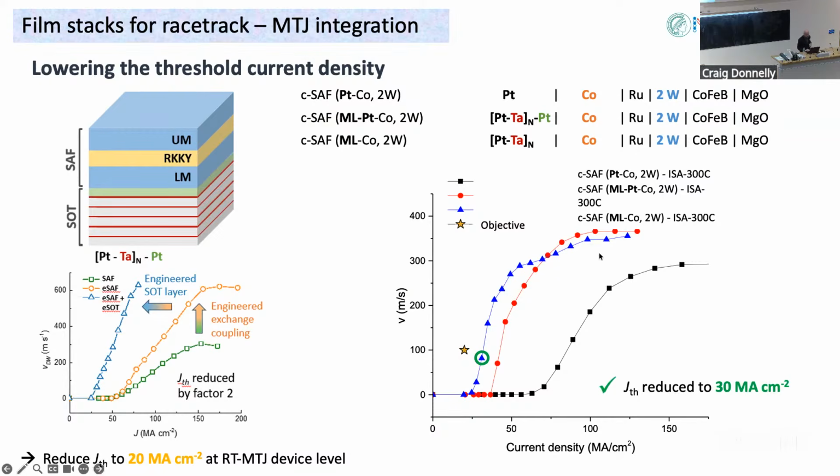And as I mentioned on Monday, we optimized, for example, the spin orbit torque layer by making it a multi-layer. We optimized the RKKY coupling through these two magnetic layers by introducing two angstroms of tungsten. So it's a lot of engineering work and some physics. On the other hand, down here, we have a different structure where the magnetic layers are now formed from a tri-layer, cobalt, nickel, cobalt, where each layer is a few angstroms thick. The whole tri-layer is 1 nanometer thick. Here we could reduce this critical current density to about 20 megaamps per square centimeter. You have to remember that number, right? That's the best number anybody has been able to create, and it took several years of work.